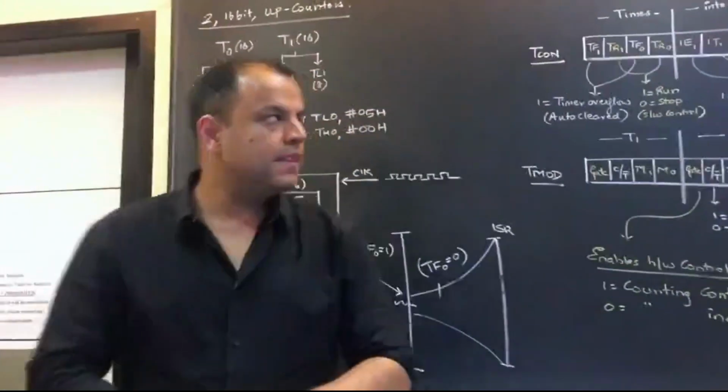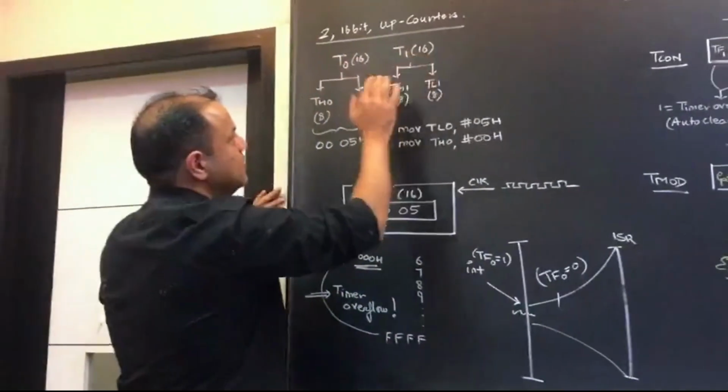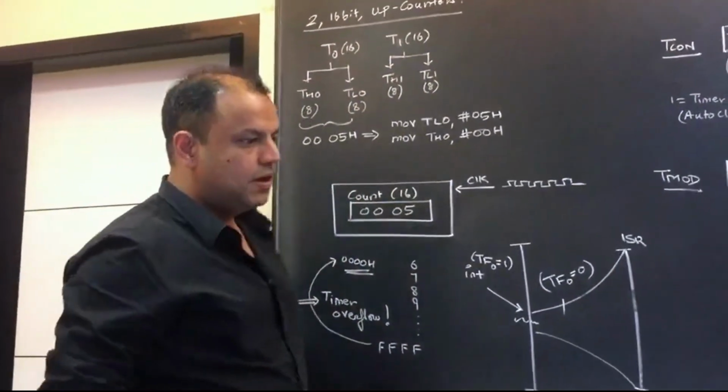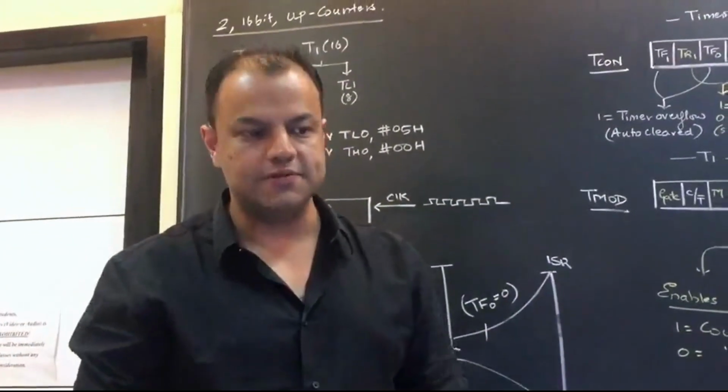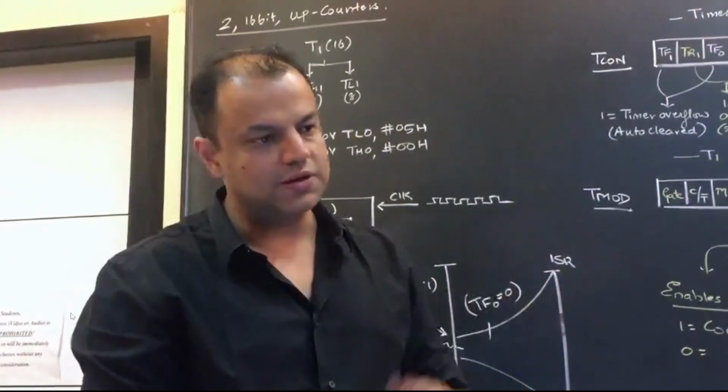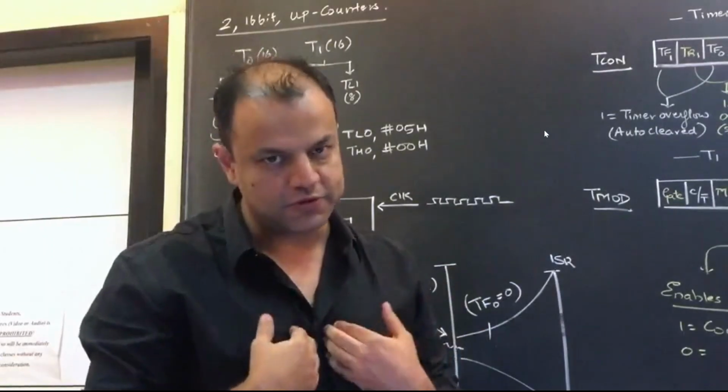Okay? Now look here. So there are two timers, timer 0 and timer 1. What is the advantage of having two timers? You can produce two delays simultaneously. I tell one timer count 1000. It is counting, and I, as in the processor, am free to do other operations. While I am doing another operation, I realize I need one more delay.